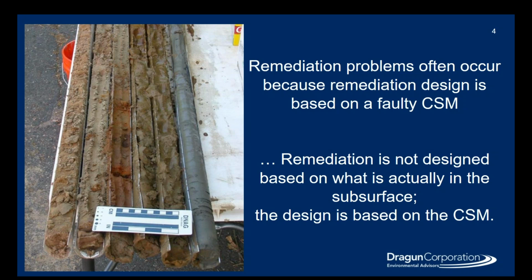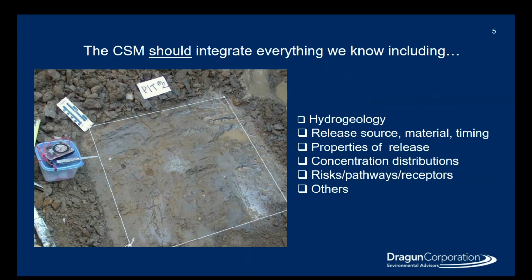This site that we're looking at here is a fairly simple hydrogeology with sand above silty clay. At this site, the CSM takes into account the simplicity of the geology, these layers are continuous aerially, and we have a good idea of how thick they are and so on. So the CSM was fairly easy to do. This CSM is not so easy.